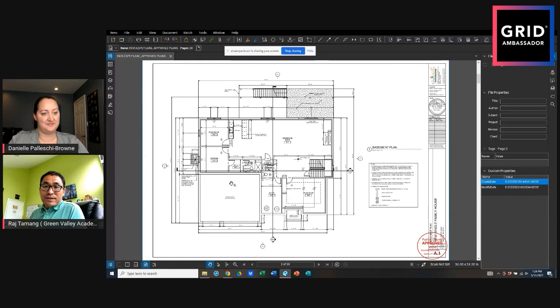But again, there's only so much you can do. You have to remember this is light frame construction, which is wood construction. With wood construction, there is only so much door and window glass you can put in, because you have to have a certain amount of solid wall in the house. So that's from the design perspective.